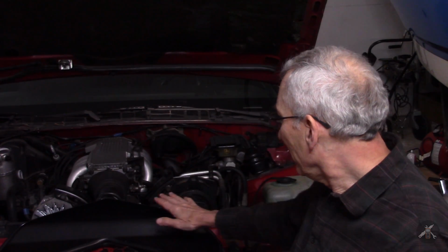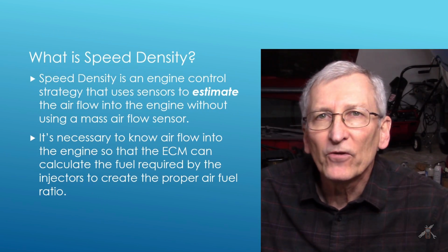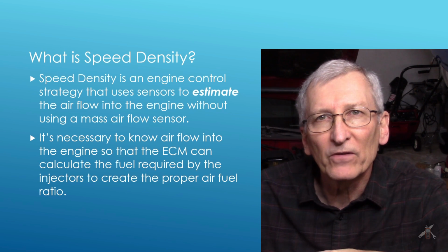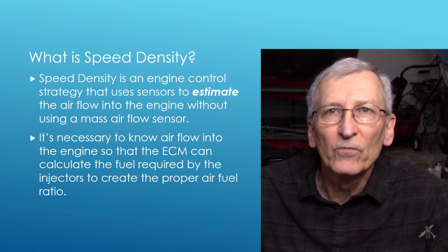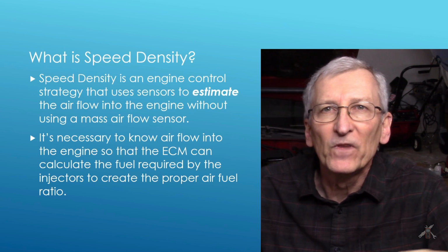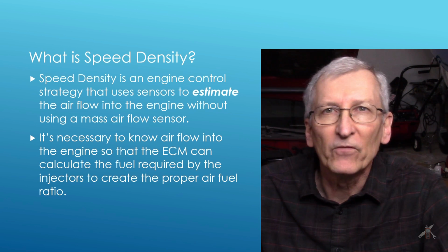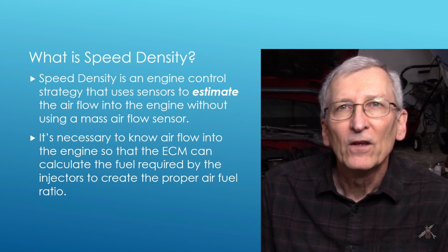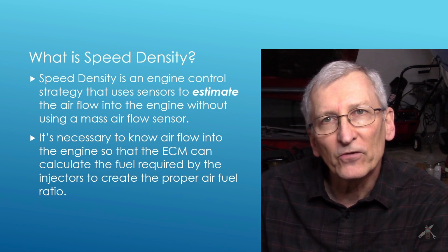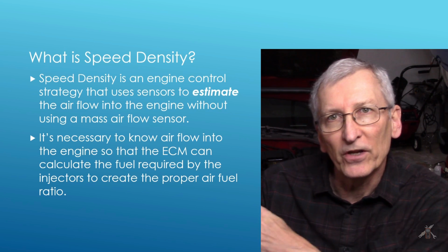In particular, my car is an 85 and the tuned port has a mass airflow sensor on it. And so it has diagnostics in a certain way that you do for mass airflow cars. The mass airflow sensor measures the amount of air that you put in the engine, and then the computer with that and some other sensors computes how much fuel they want to put in the air and it gives you an air-fuel ratio.